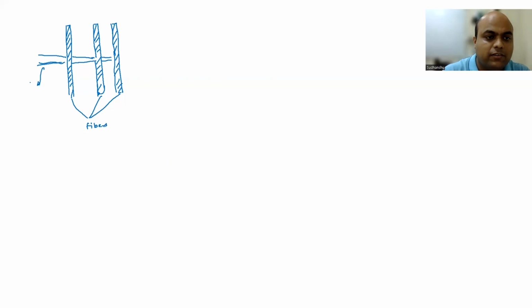And then this is your crack. So crack is going from the fibers, right? So if you see, this is your crack area. Okay. So you have fiber and crack is passing through that fiber. Fiber has not fractured. Okay. So what you see is the bridging of the crack because of the presence of fibers, right? So fiber has not fractured. So here what you see is crack bridging. Now this will enhance the fracture toughness also, right?